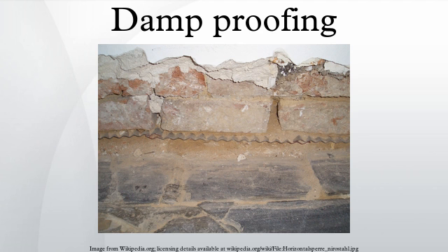Materials widely used for damp proofing include flexible materials like butyl rubber, hot bitumen, plastic sheets, bituminous felts, sheets of lead, copper, etc. Semi-rigid materials like mastic asphalt, and rigid materials like impervious bricks, stones, slates, cement mortar or cement concrete painted with bitumen, etc. Also stones, mortar with waterproofing compounds, coarse sand layers under floors, and continuous plastic sheets under floors.